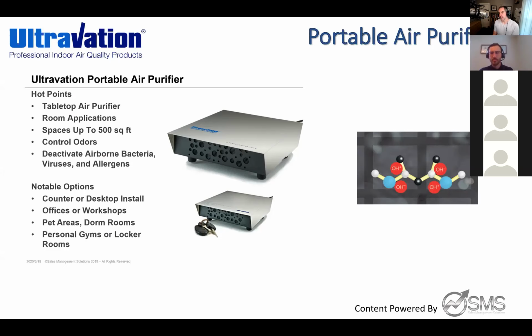Yeah, and I should note in here, this is a little bit different because it's also actually doing filtration. There's a washable air filter in there. So you have the filter plus the UV lamp plus a strip of carbon bricks right at the exit point on the front of the unit. The turbine fan is mounted underneath the unit. That's why there's little rubber feet to give you a little bit of a passage of airflow, but that pulls the air up into the box, passes through the filter, passes past the UV lamp, and then out the front there, which is going right through the carbon bricks, which have the titanium dioxide on them, which is creating your PCO as well. So yeah.